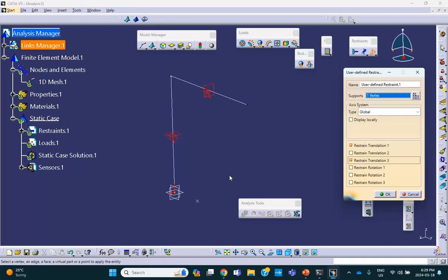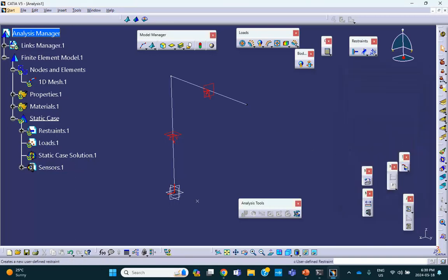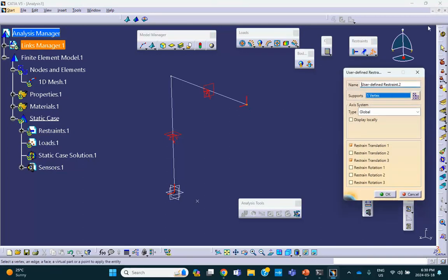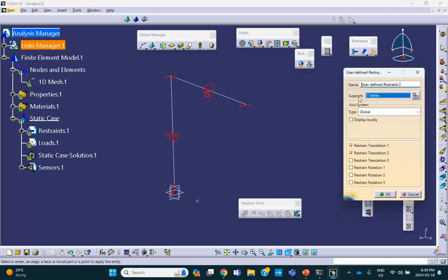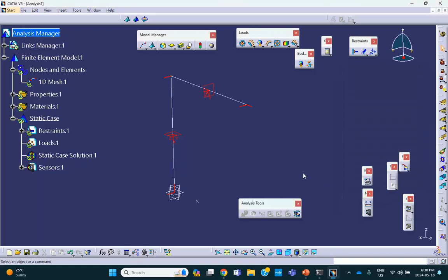All right. So that's good. This fellow cannot move in the direction X because it has to stay in plane, and cannot move in the direction Y. That makes it a roller. All right. And I'm going to prevent rigid body motion here. So one point, for example this point, just cannot move in the direction X. All right.